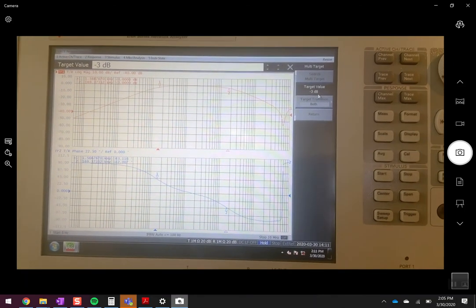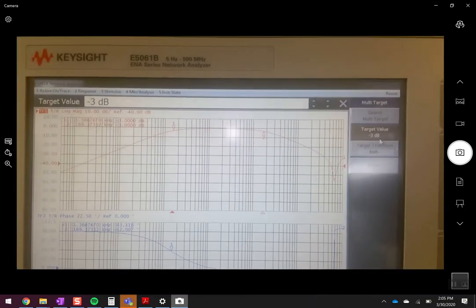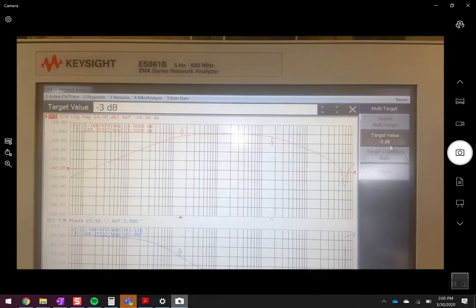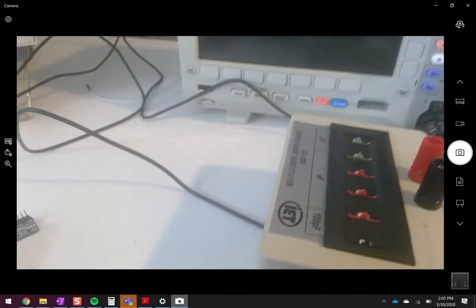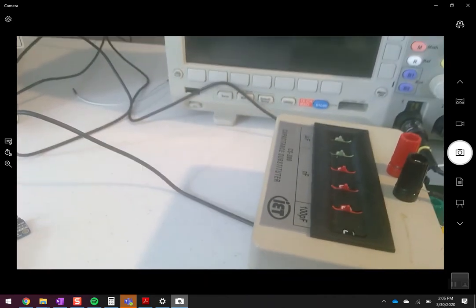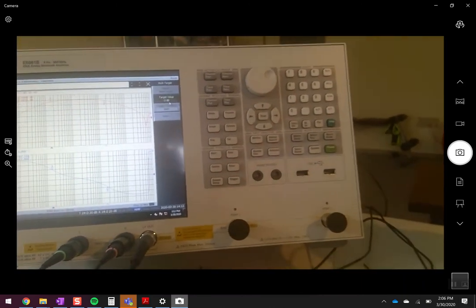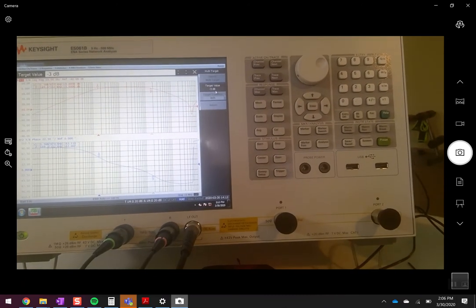And it says, well, you hit that twice. I hit it once at 1.56 kilohertz, so that's the low frequency one, and then another at 170 kilohertz. Well, that doesn't seem that great. And it's not. I was supposed to get 200. My simulation clearly said 200. So something clearly is going on when we put the real components together. It's not because the simulation has an error or that we made an error in a computation. There's just got to be something that we're ignoring or not accounting for.